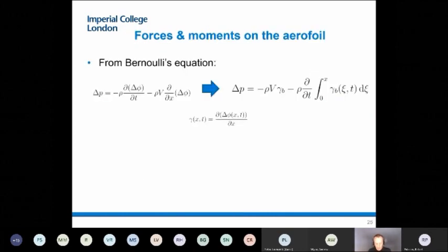So we have then solved the wake. We have a differential equation that tells us what's going on in the wake. And now we go back with that relation we had before between delta P and delta gamma, and we can obtain the pressures. So since we wrote gamma in terms of the derivative of phi with respect to x, then what we can do is to replace those into that equation there.